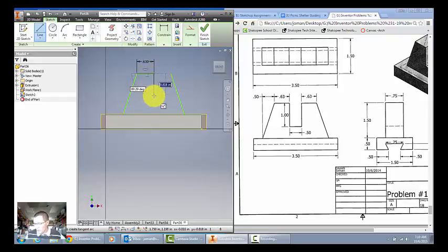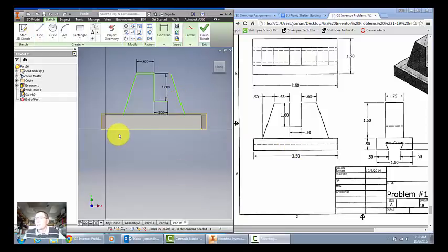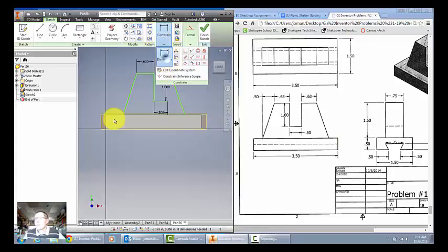1.63 in, 1 down, 0.5 over. And I'm going to find out real quick here that something's not quite right with this. You can tell my spacing's not done well. So we have to go back and calculate. It looks like I forgot to add in the 0.5 that was over here, so it's actually 2.75 total right here. 3.5 minus 2.75 is 0.75, or 3/4. Divide that in half, you get 3/8. As a decimal, that's 0.38. So let me redimension these 2 spots.